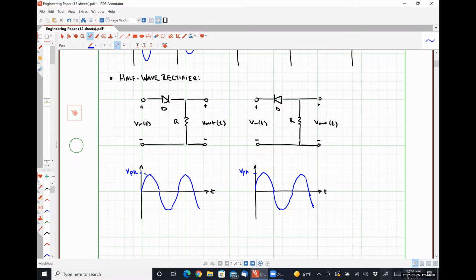It winds up using the peak value of the instantaneous voltage, which would just be the RMS voltage multiplied by a factor of square root of 2, okay? So whenever I'm mentioning this voltage, that is the instantaneous value of the voltage. It is not an RMS voltage whatsoever, okay? I want to be very, very clear about that. V peak has units of volts, not units of volts RMS.